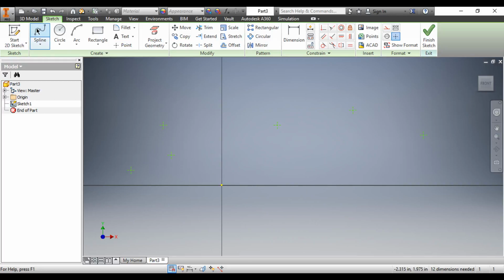And now let's create a spline. Click Spline Interpolation. As you can see, now the cursor is yellow, and when I place the cursor over the point, it turns green. Again, make sure it is green. Again, click here, click here. You can either click OK or Escape.